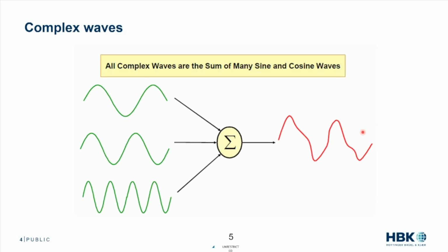But it's also important because we can take this motor excitation, and this is a very ugly motor wave, I know. But this is coming from a sound and vibration presentation. Fascinating how similar the two are. We can take this kind of complex wave and break it into elements: this element with this amplitude and this frequency, this element with this amplitude, this frequency, and this phase. We can break it down into its individual waveforms, which I think is really interesting and an exciting way to analyze these things.